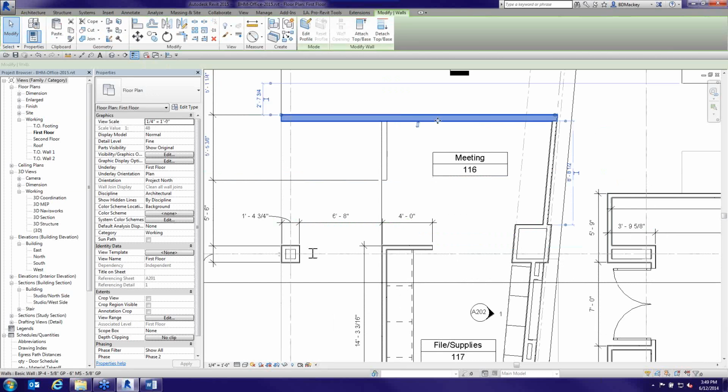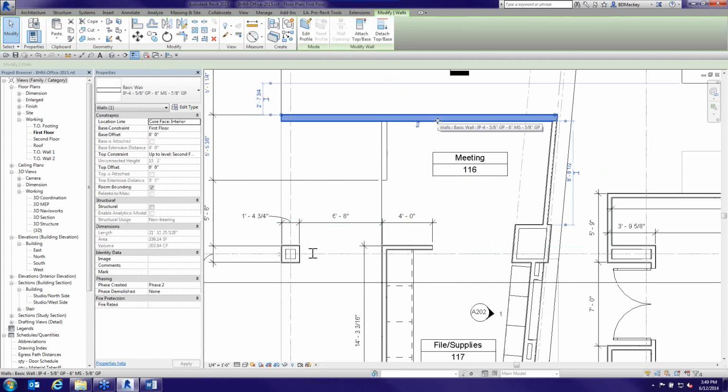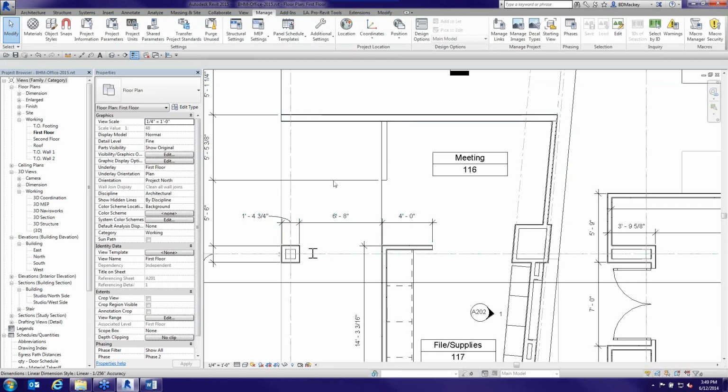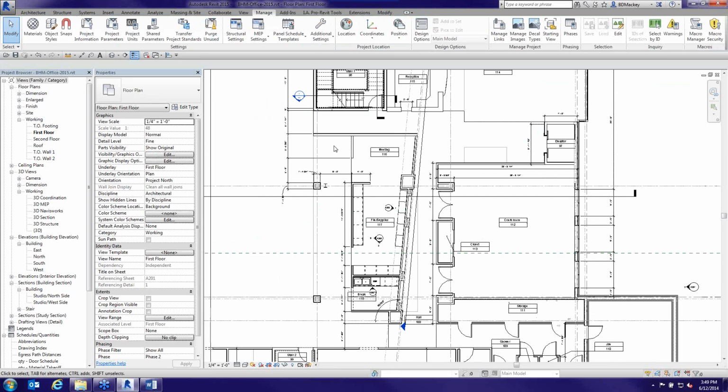If I did copy it from this view and switch to another view to paste it, then, mentioning copying from linked files, yeah, if I copy from the linked file, then the architect's walls more than likely aren't structural, so you might have to check that dialog. So yes, that's a very good point. But if I can see it to copy it, my discipline's got to be coordination or architectural so I can see it in the first place. But yeah, absolutely. If you're copying and pasting, pay attention to discipline, things like that, all those normal nuances that give us headaches in the real world.